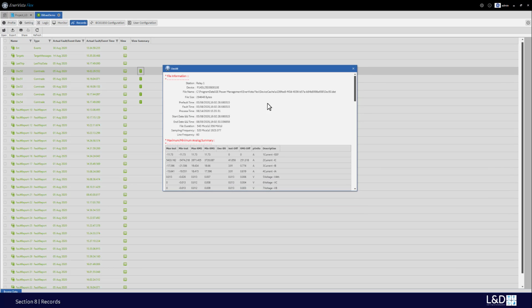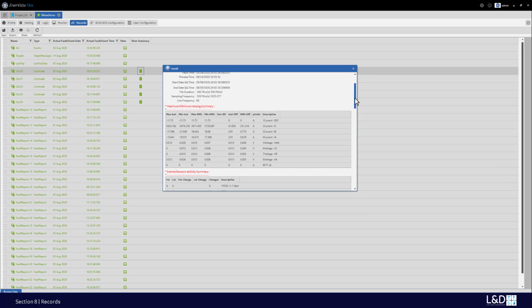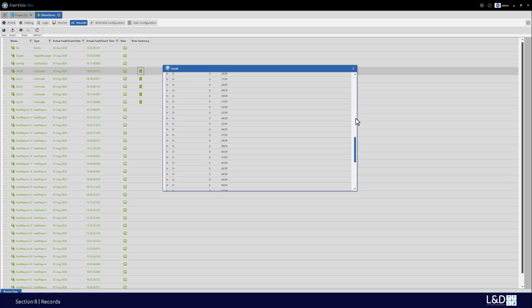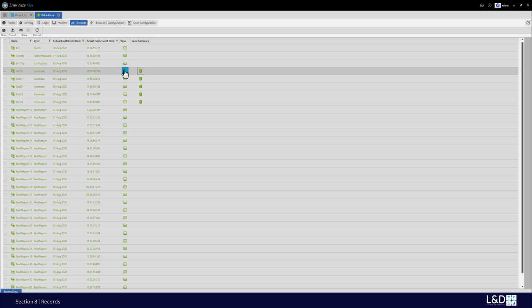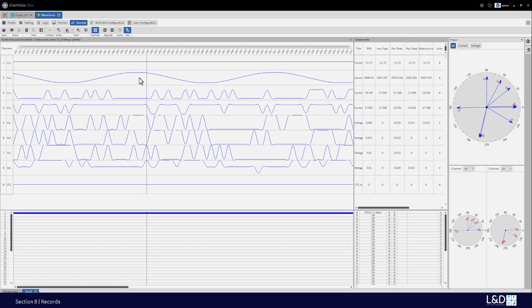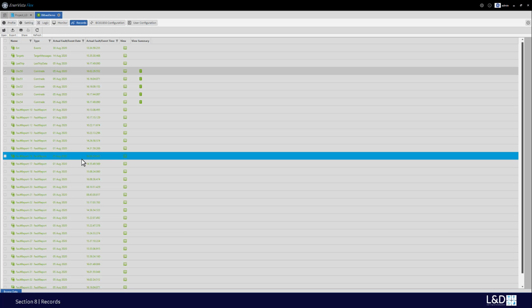So we can see where data is saved, what the parameters are, and this is the view of the waveform. So we can see the waveform with the current, we can see the values, phasor, we can see the digital inputs. We can know this is the phase TOC pickup start. Again, we're going to introduce more about events and oscillography in the next 103 videos.